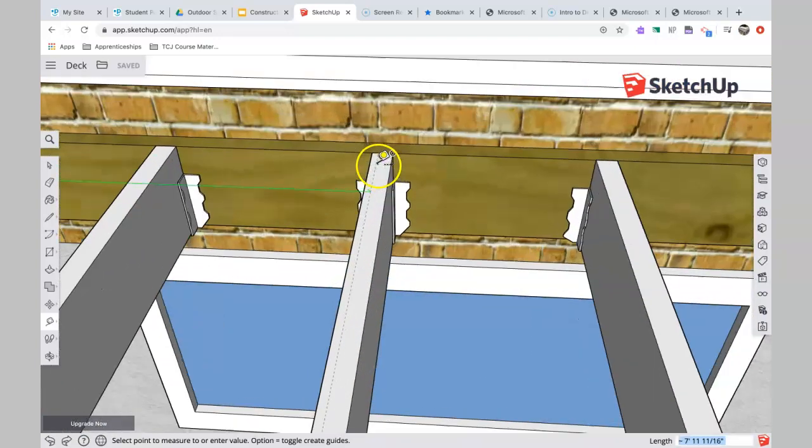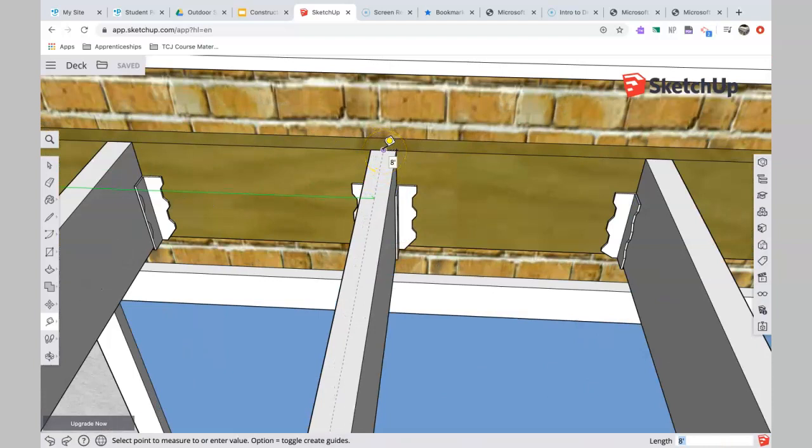And let's go here to the center of this one. You see that is 8 feet. So from the end of the deck to the center of this is 8 feet. And that's important. If this was a house, so forget about a deck for a second, and we were putting plywood on this floor, then plywood comes 4 foot by 8 foot. And so you would be able to fasten the piece of plywood to this joist and then start a second piece on the same joist.